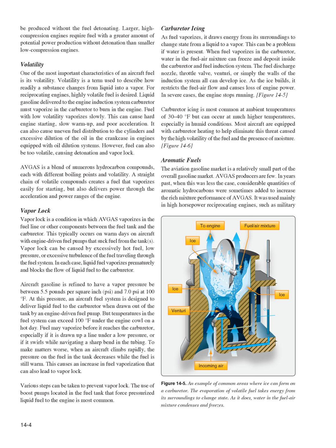The fuel discharge nozzle, throttle valve, venturi, or simply the walls of the induction system all can develop ice. As the ice builds, it restricts the fuel airflow and causes loss of engine power. In severe cases, the engine stops running. Figure 14.5.